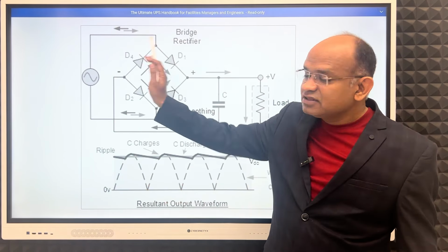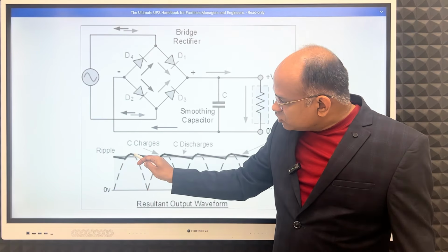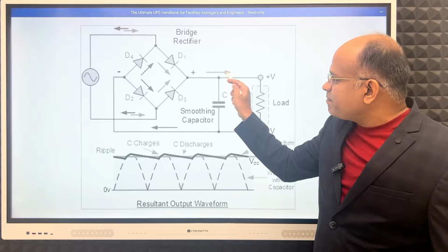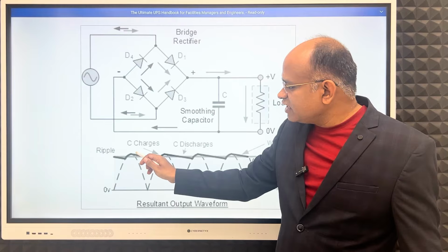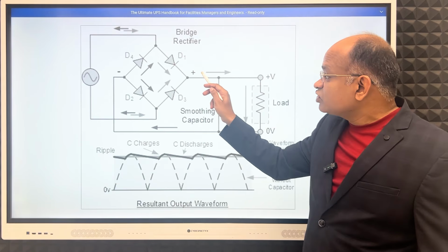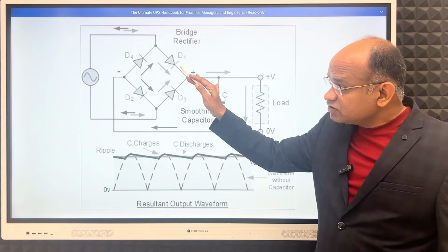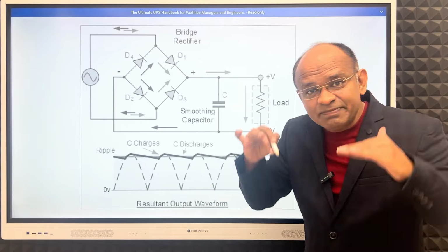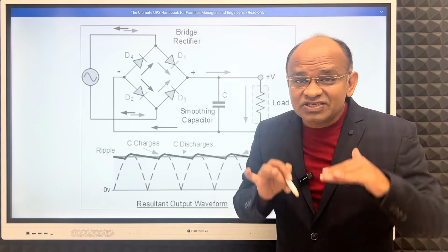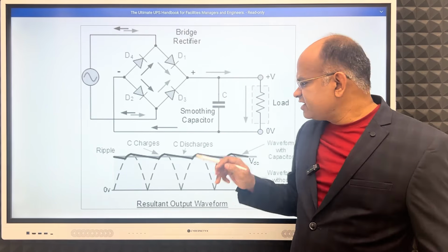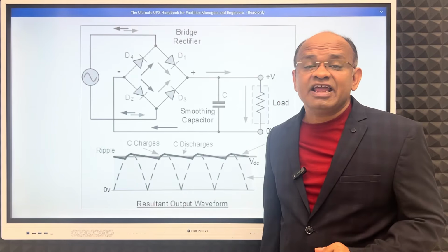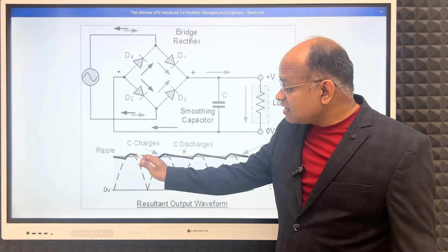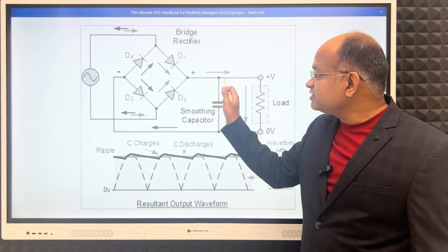We have seen the AC cycle. So this will stop because it has already done its job till this point. It will stop taking energy from the source because the source has depleted. You got less voltage there, so the load will not be catered by the source. Then from where does this current come? This current is coming from this charged capacitor.